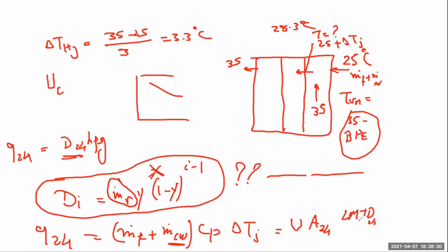Yes, that means, Doctor, that we basically now have the tools in our hands that we can use for analyzing problems associated with the brine recirculation MSF system. For the once-through MSF system, it's exactly the same, but we do not have a brine recirculation part. We don't have a heat rejection part, which means that it is simpler to go through the once-through system compared to this. We don't have time to show you the other presentation that I was preparing.